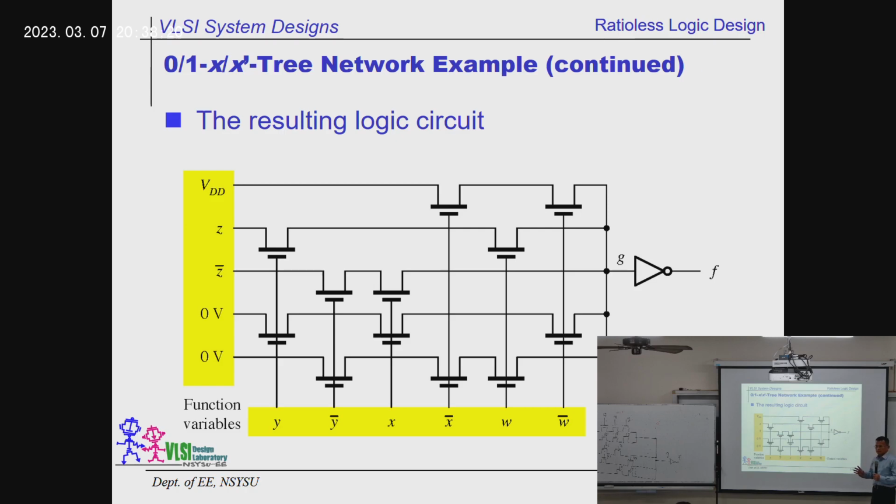Now, let's see what the difference is, okay? Now, this is the implementation in the textbook: W, X, and Y. All right? Okay? How do we calculate the performance? Let's check. Basically, you got to check two things: how many transistors you need, and what is the longest path? Longest path stands for the longest delay.